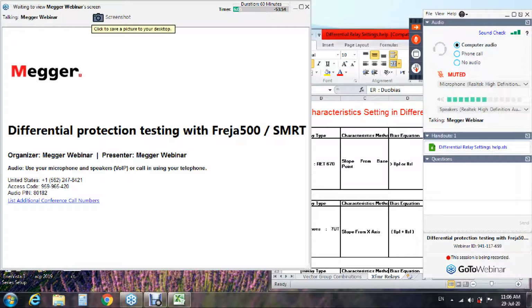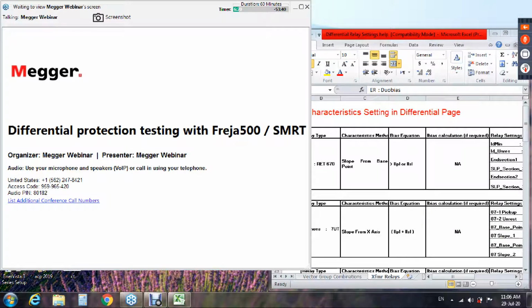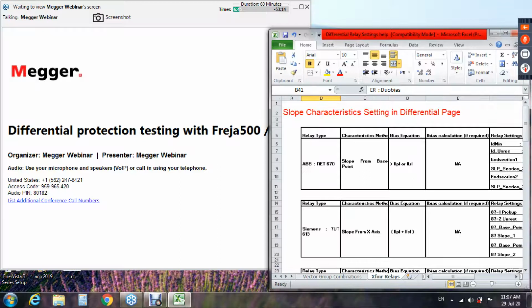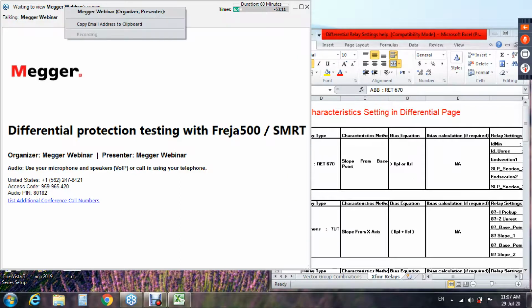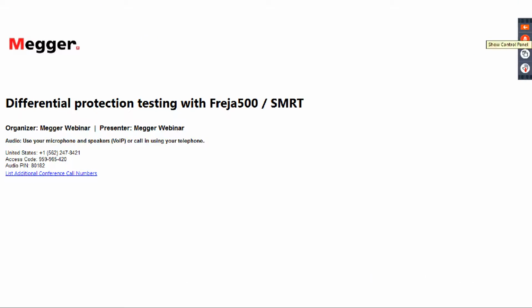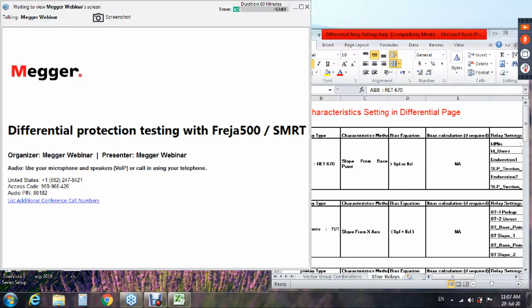Now, the downside of using differential protection is that it requires too much cost compared to other protection principles, but nonetheless, this cost is worth the trouble. Now, this is differential protection in general, but what about transformer differential? When you have a transformer as your protected object, let's take, for example, this transformer. It's a vector group of DY1. It has an HV side of 500 kV and an LV side of 230 kV. And the rated power of this transformer is equal